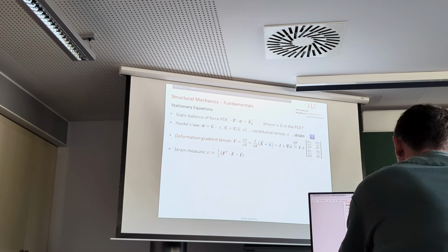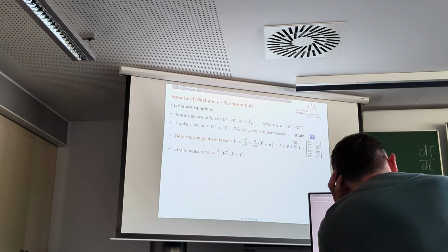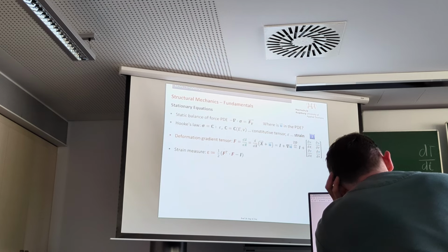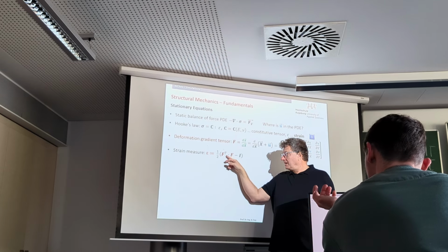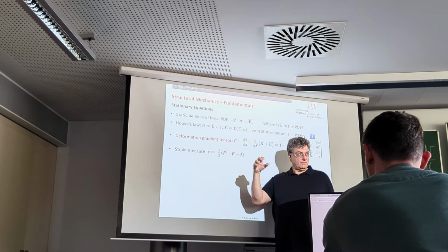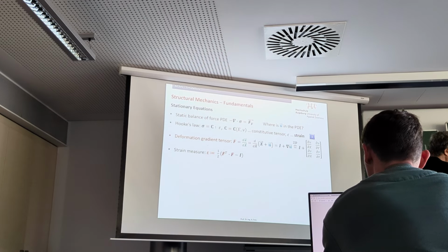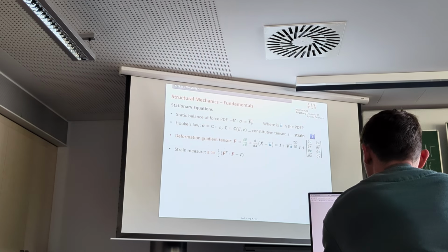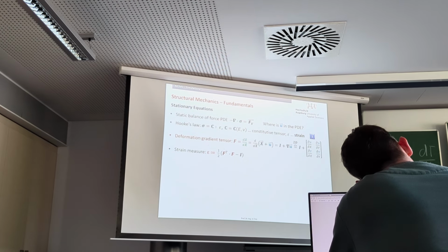And you now maybe understand why it makes sense. From the components of the displacement, by using that type of definition here, we cancel out the rotation part, which is not contributing to stretching. We are only leaving the parts of the movement which really contribute to stretching the material.